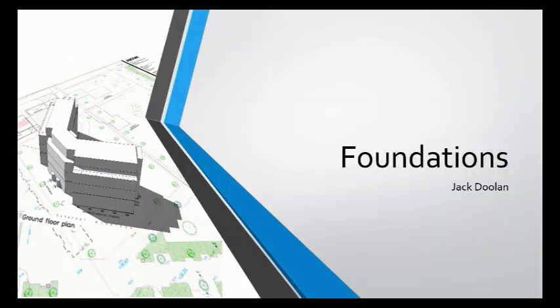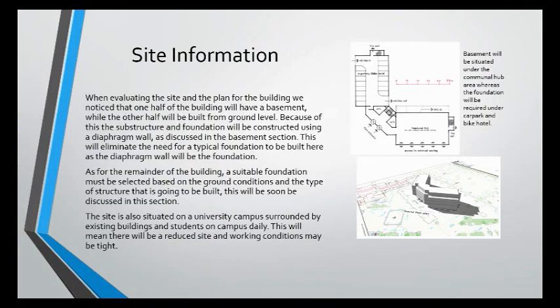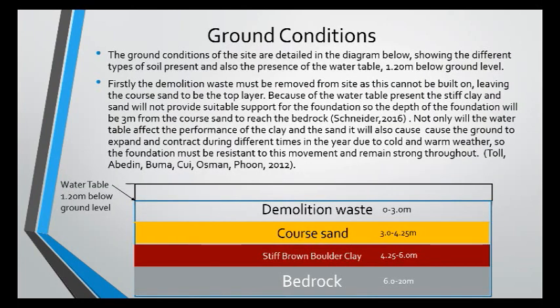Hello, my name is Jack and I'm going to be talking to you about the foundations. When evaluating the site information, we noticed there would be a basement on one half of the building. This area does not require a foundation, as the basement walls will provide the building with suitable support.